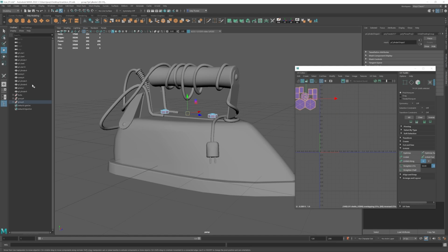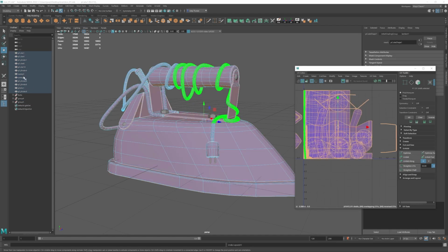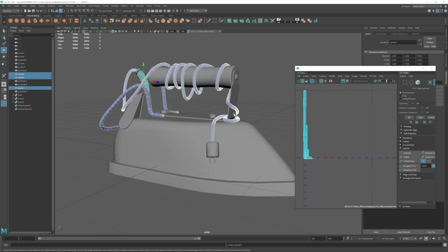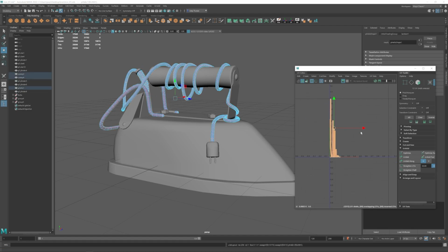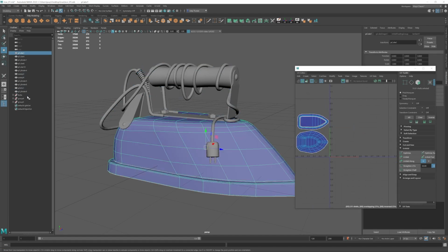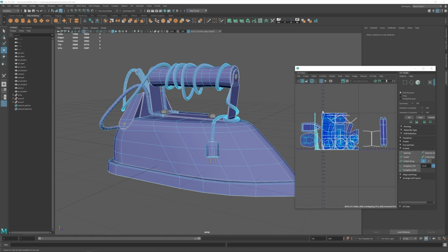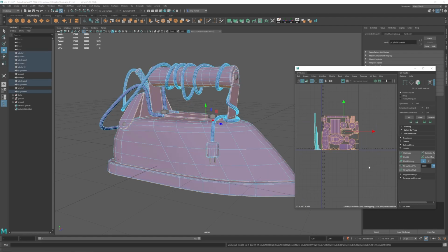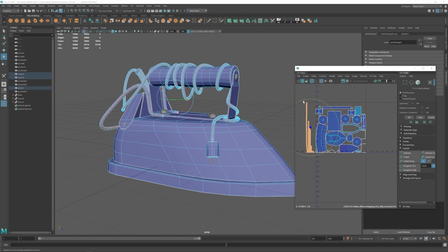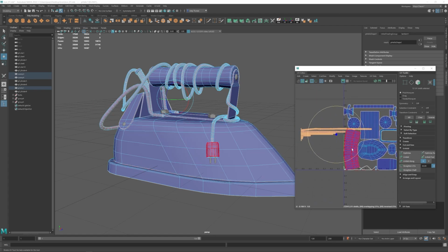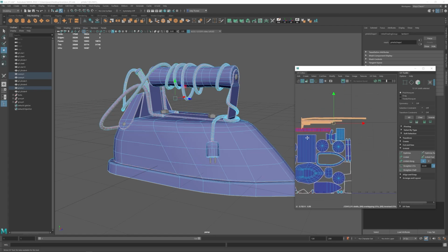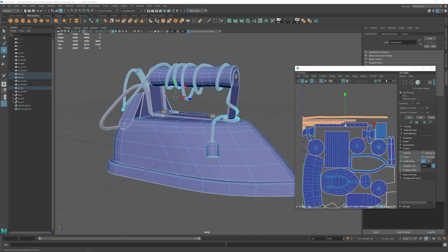Alright, so now that all those objects that are sharing the same UV space are pushed to the side, I basically want to lay out all my other single objects. So I'm just going to move over all the sweep meshes since they're already laid out, basically taking up the full length in my one-to-one space. So I'm going to push those to the side, select all the other objects, and I can Control L to lay them out. Then I can go select all my sweep meshes and I can start positioning them to fit in the empty space in my UV map.